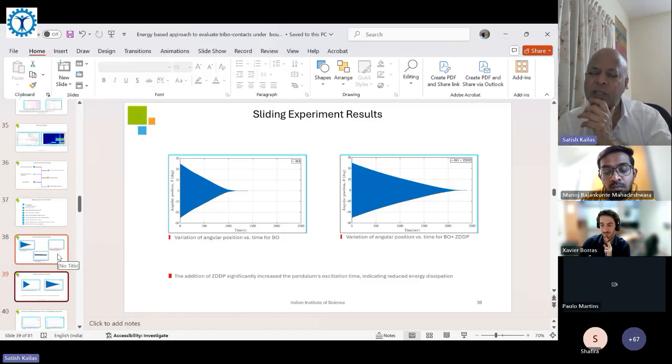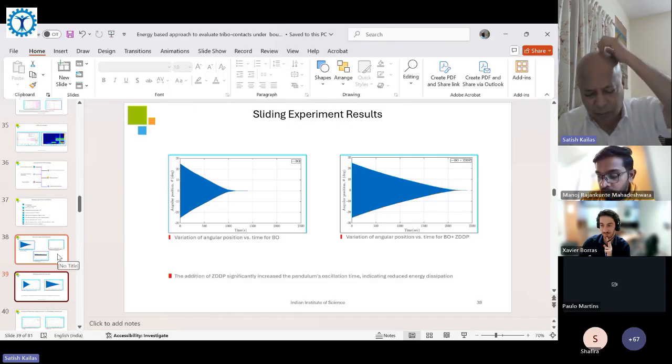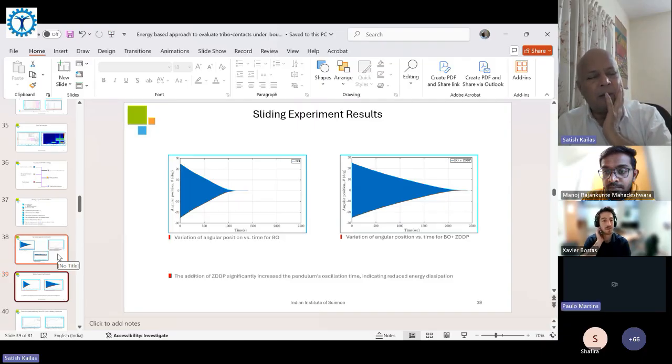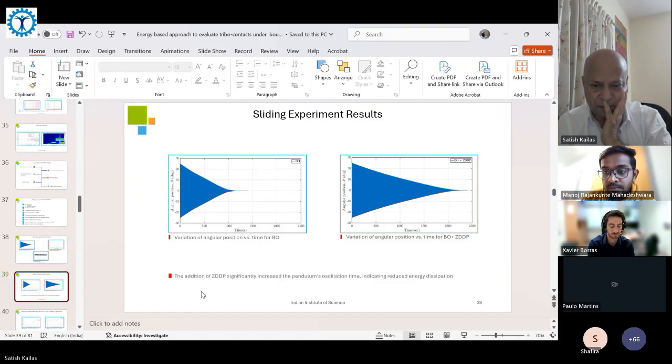Correct. So what we do is, when we go to the second series of experiments, we do again a no load test, so that we know if the bearings are degrading. But in the present machine we have aerostatic bearings, so there is no question of any degradation.